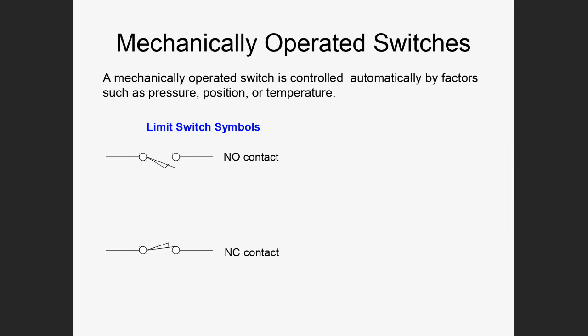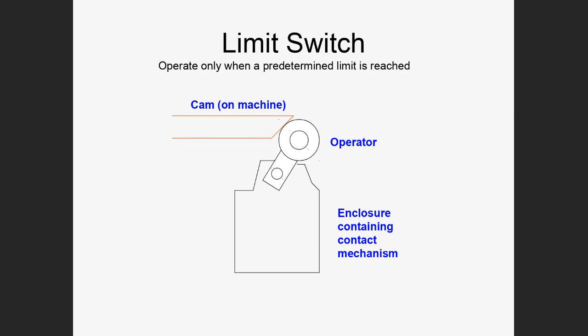These limit switches, you've seen this symbol in your simulation software. I've worked with these extensively with some design stuff that I did years ago. You can use these to find the limit of motion. The actual switch looks like this. There's this body that's usually sealed to the environment, so it's waterproof and dustproof. The actual switch is located in this body, and there's this arm that moves. Sometimes they'll have a wheel, and sometimes you'll see these without a wheel and just a lever.